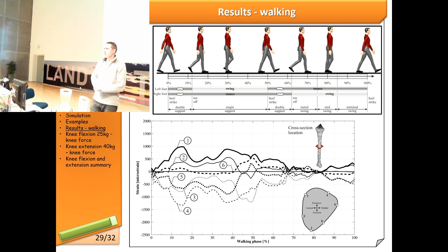So you have a heel strike, you have bending, then you have a toe off, you have bending, and then when the leg is in the air, basically they are just inertial forces and some residual muscle forces that are bending the leg. But the leg is bent most of the time during walking. Of course, it's compressed, and you can see that the whole thing is kind of shifted towards the compression, but the dominating load is bending.